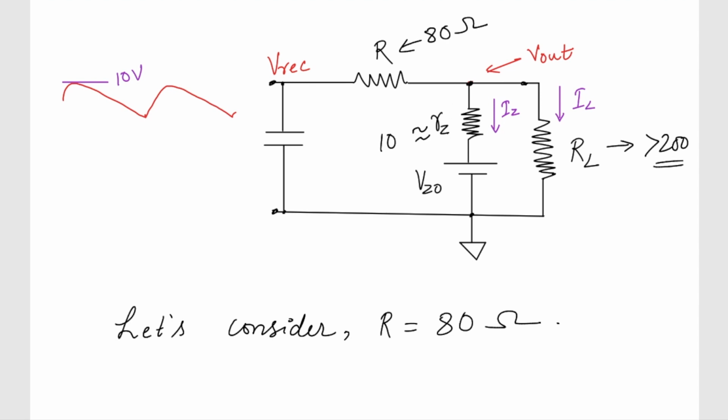Okay, so what is going to happen is, if I see the impedance that is seen by this capacitor, because this will define the lower value. This capacitor C is going to discharge, and the RC time constant is defined by the resistance of this network.